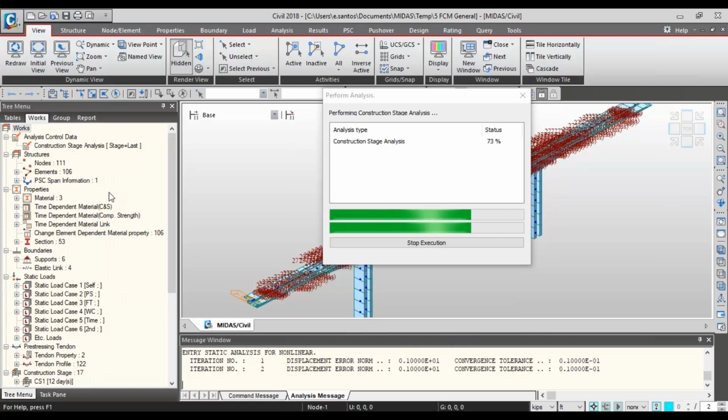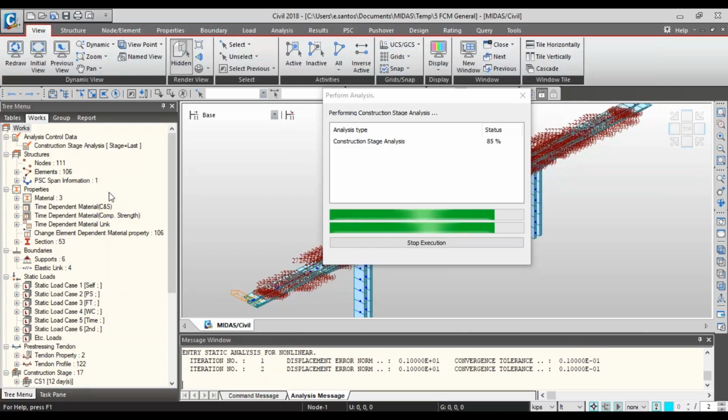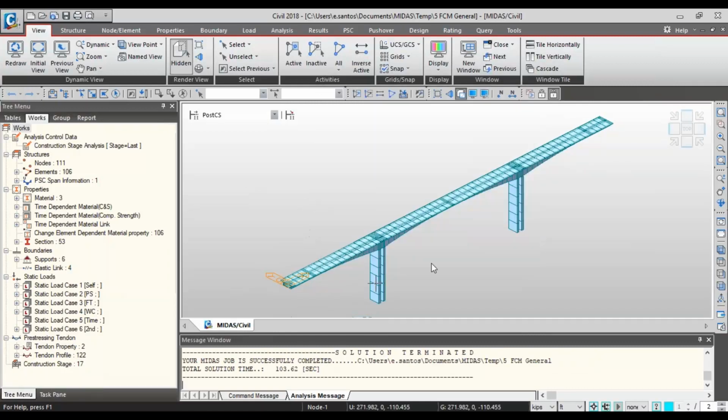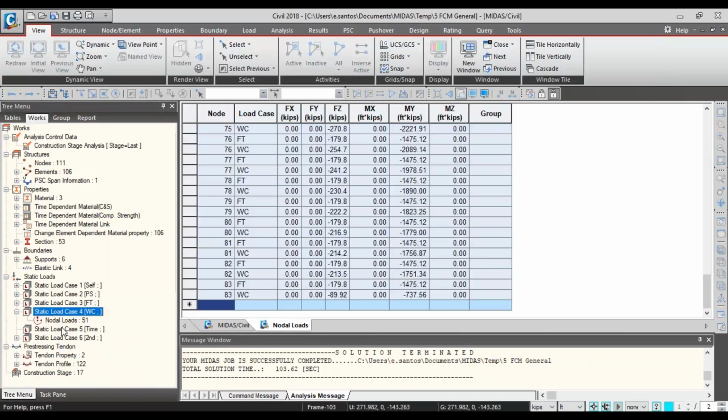After running the construction stages, you can also perform seismic analysis. You can perform either linear or nonlinear analysis, it's up to you. After running this construction sequence, we're going to check out the different forces that we can obtain due to the loading that we find in the wizard. Another thing is that if you want to change this loading, you can just right-click on the different loads and click on the table.